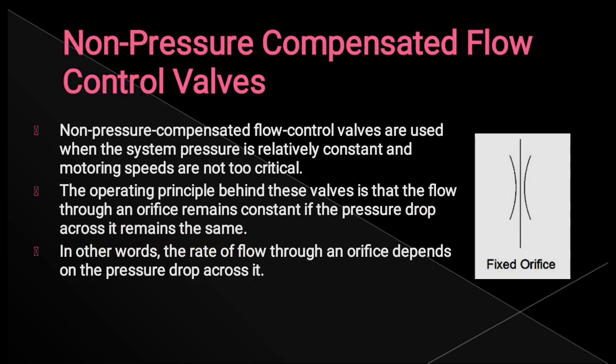It is fixed, so the pressure drop is also considered the same in the non-pressure compensated flow control valve. In other words, the rate of flow through an orifice depends on the pressure drop across it. The amount of flow depends upon that pressure drop.